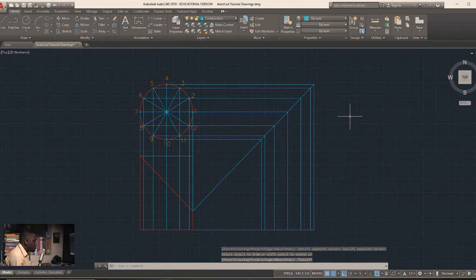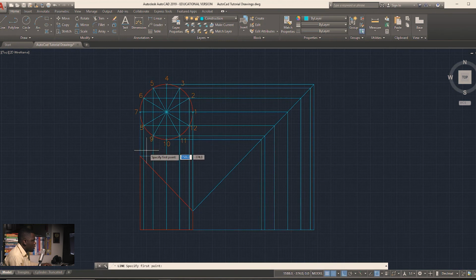And then now from here I'm going to project all of these points across. So wherever they strike this surface here, I just bring them across. So if this surface was at 60 degrees, it would be the same process. If it was at 30 degrees, same process. No matter the angle, when they hit here, you just bring them across. So this point, rather, at 7 came down, hit the top of the drawing, and it went across. So I'm just going to pick it up from here and extend it.